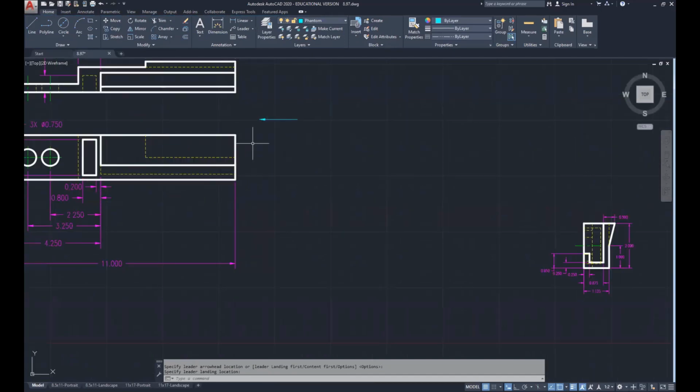that. I want this arrow to be bigger, so I'm going to select it. I'm going to use the scale command, scale at 2 times. I'm going to go ahead and explode any properties that it may have. Use the explode command. I can make this line a little shorter. I could have also trimmed different things of that nature. I didn't have to do it this time.